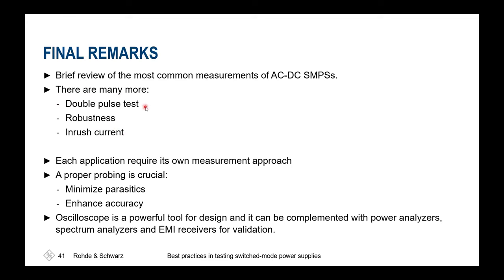And especially the double pulse could be of more interest in the future for you because double pulse does not necessarily force you to only qualify how is the behavior between the high side, low side gate. It could also be used to qualify the overall system behavior so that you're using a reference load to your complete system and then do the analysis on different switching patterns, different switching schemes, like we've seen previously from Florian's presentation with the spread spectrum clocking that might be used.